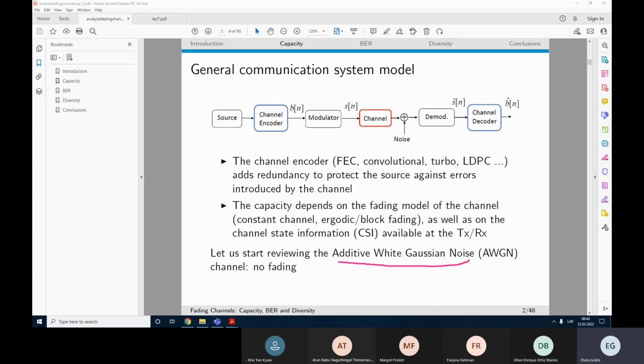We also noticed that because of using these filters, we actually improve our symbol error rate, because we do not take all the bandwidth of the noise, simply due to the fact that we use filtering, and the filtering limits the bandwidth. For example, we had these square root raised cosine filters designed, which limit the noise bandwidth, which in theory is infinite.